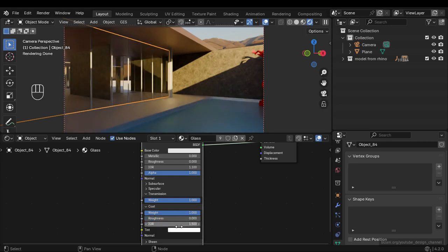And I increase this value of RY to have more reflections. Let's go to 5. Now, if I increase the roughness here, you see what's reflected is being rough, while what's transmitted is completely clear. This is the roughness of what's transmitted.